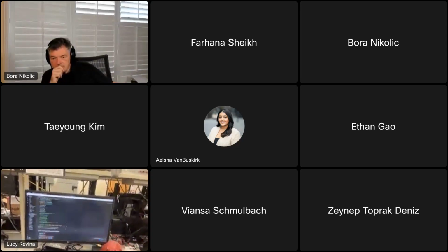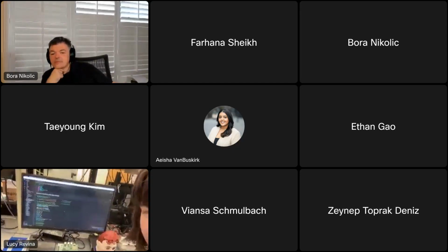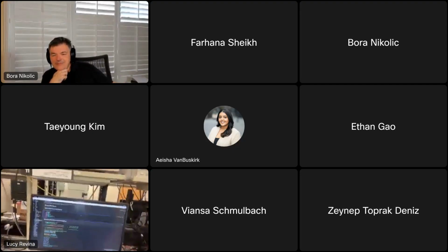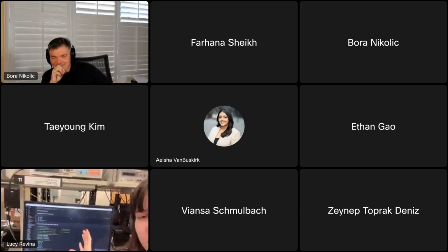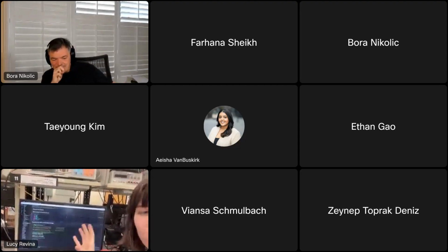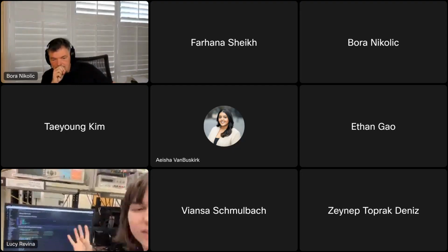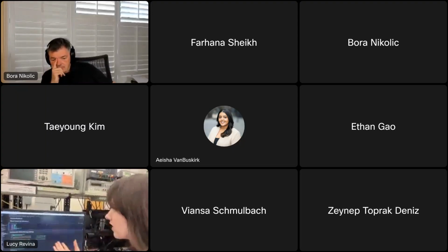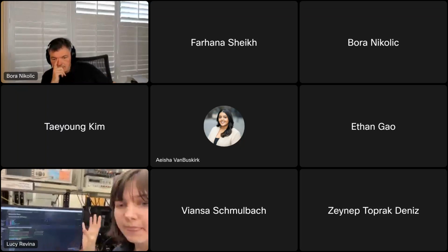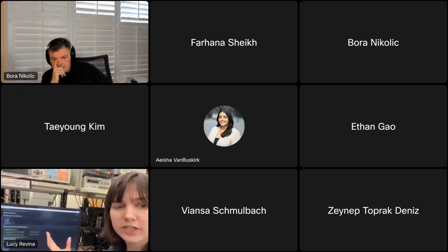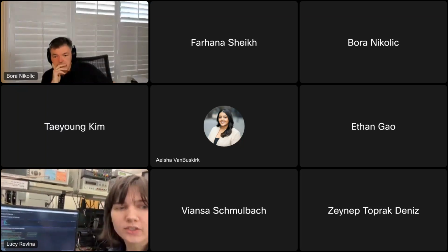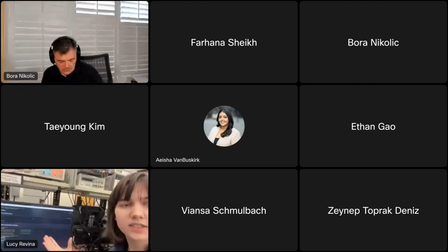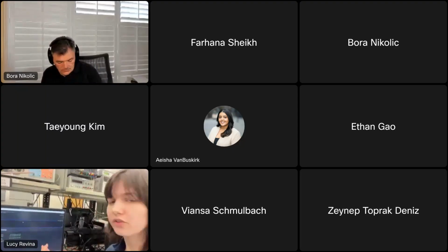I'll just scroll up to the top. So you can see it's a real notebook, again, not just screenshots. This is actually what we're using. So you can see here we have a Python notebook that allows us with just a few clicks to automate a lot of characterization of the chip's electrical qualities across different corners. We'll show you this again in a second once we're actually showing what the workload looks like. This is how we can sweep and characterize.